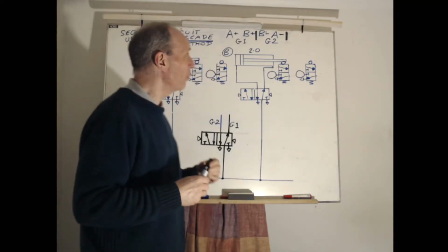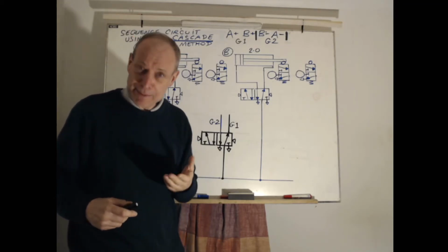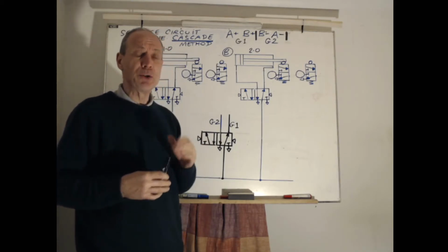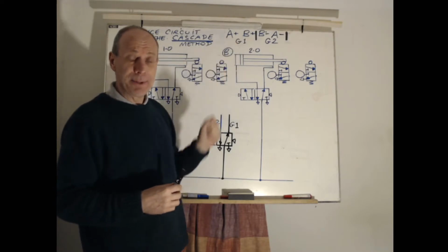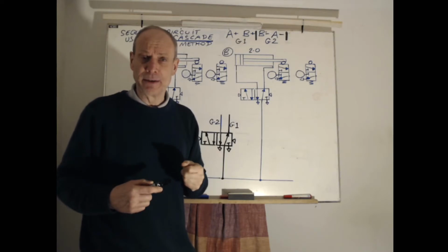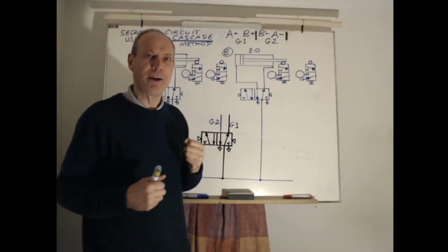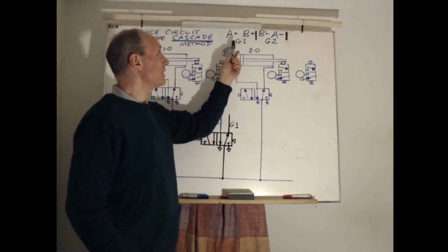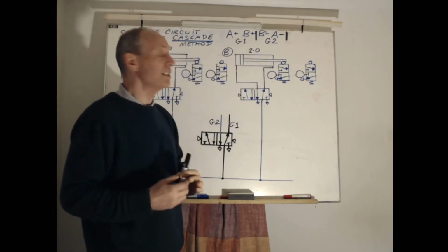On the last talk we deduced that the sequence circuit, A plus, B plus, A minus, B minus, works successfully, but when you start to mix up the sequence operations you can get trap signals. We found that A plus, B plus had a trap signal problem before going to B minus, A minus, where another trap signal developed. And we deduced that these can be eliminated using the Cascade circuit method. We also deduced that if you split it into two halves, you could class the first half up to the trap signal as G1 and the second half as G2.